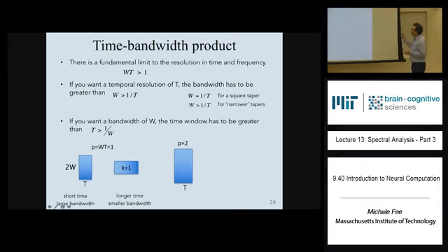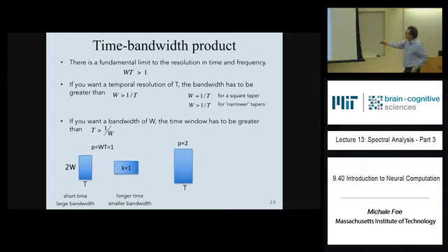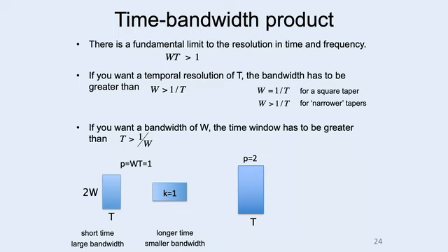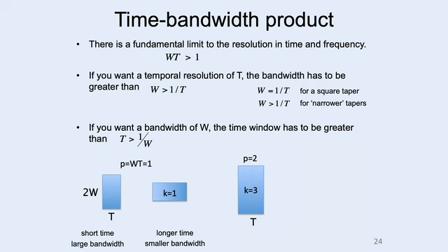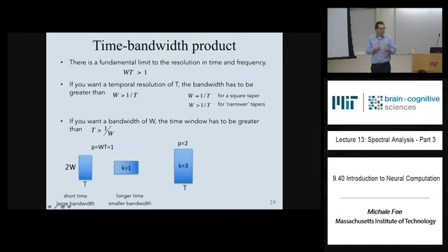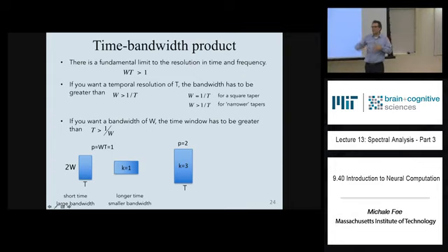Well, notice that if the time bandwidth product is 2, how many functions do you have? Why does that matter? Because now you have 3 independent estimates of what that spectrum is. So sometimes you would gladly choose to have a worse resolution in time and frequency because more independent estimates means a better estimate. Sometimes your signal might be changing very slowly, and then you can use a big time bandwidth product. It doesn't matter.